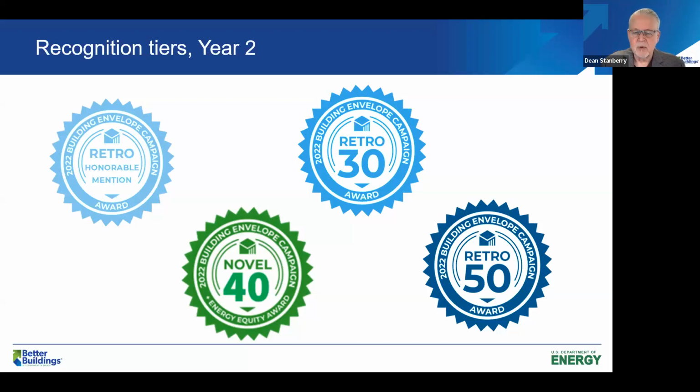Now we're at a point where if we don't start looking at some of these harder items, like, is the building really sealed? Do you really have enough insulation on the cladding of the building, as well as the windows, the fenestration in the formal terminology? You're going to be letting out a lot of that energy, or letting it in one way or another, and the building will not perform as well as a result.